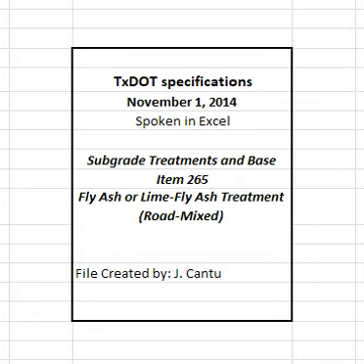Removal and disposal of existing asphalt concrete pavement will be paid for in accordance with pertinent items or Article 4.4, Changes in the Work. Asphalt used solely for curing will not be paid for directly but will be subsidiary to this item. Asphalt placed for curing and priming will be paid for under Item 310, Prime Coat.